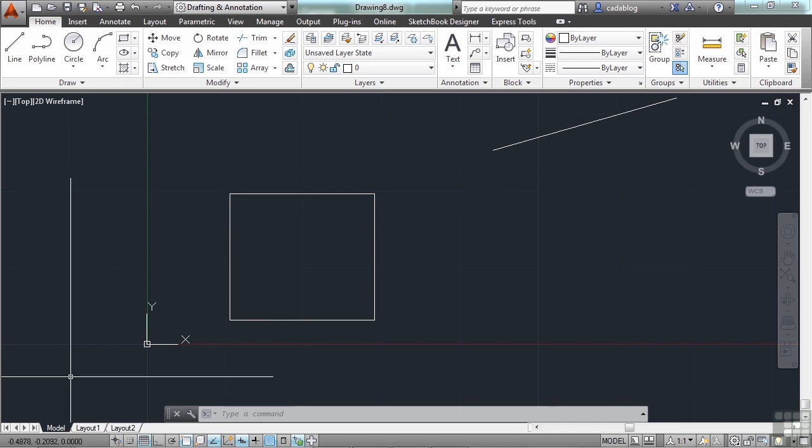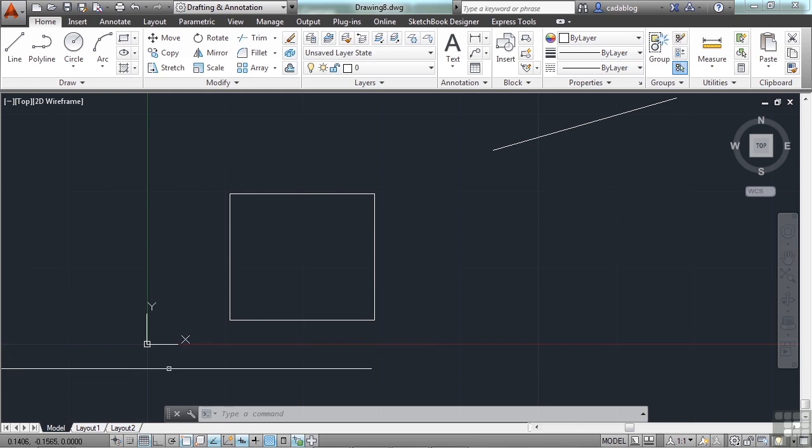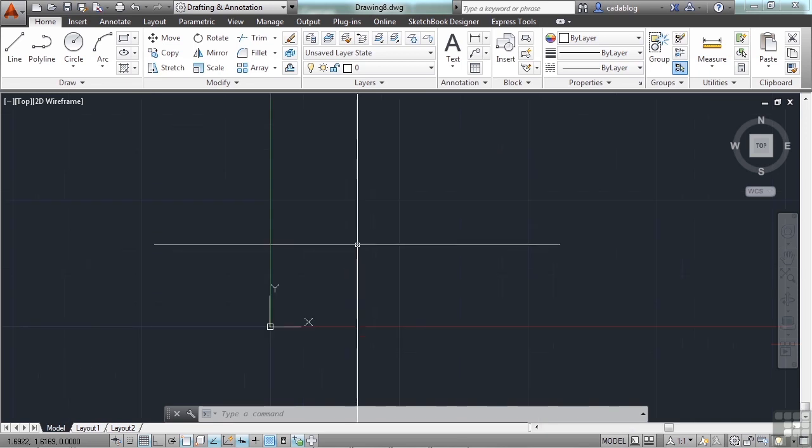It's the same sort of thing. When I move over here to the left and lower of the UCS icon, you can see my coordinates are negative. To the top right, they're positive. And the X and Y become positive and negative accordingly. You can draw objects to distances, or you can draw them to static coordinate points. For example, let's draw a line that starts at the origin and goes to coordinate 3, 4.